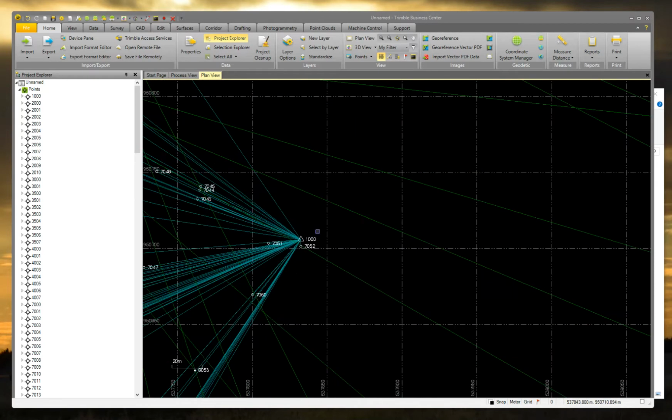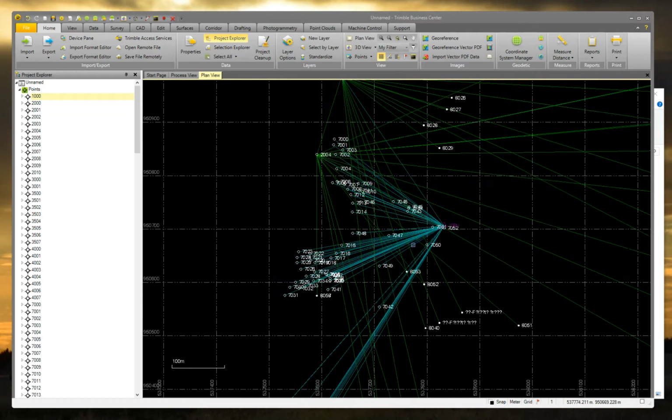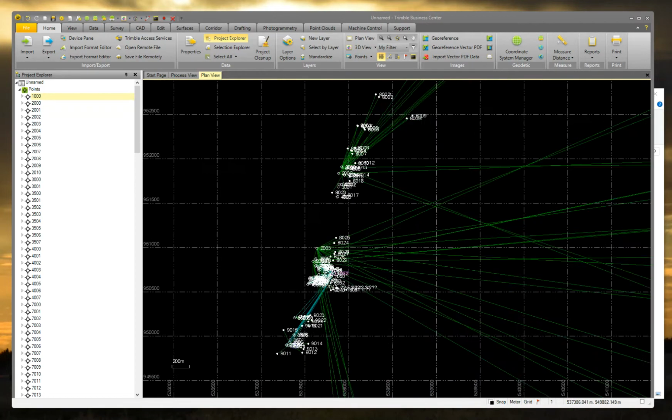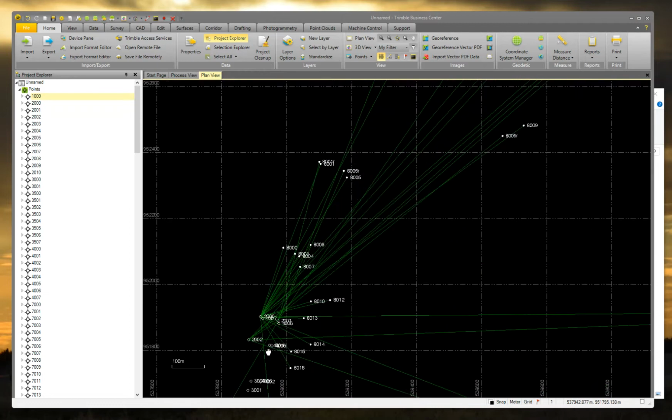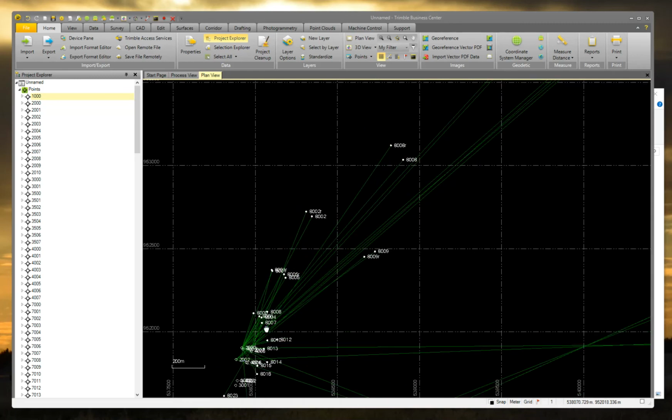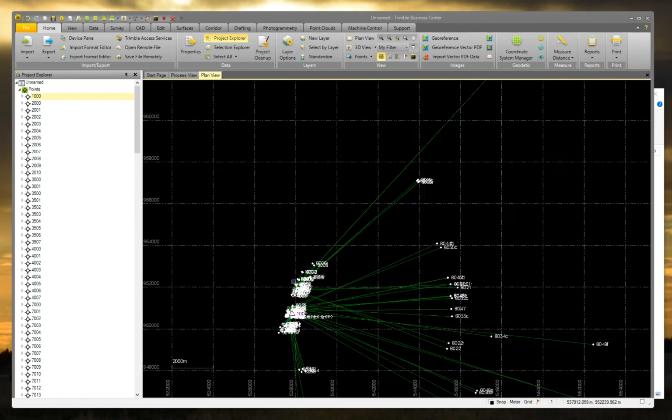You can see that your GPS base station 1000 was running. You've got a lot of unprocessed vectors here at various points. And up here, again, you set total station. I'm not sure why, but there aren't GPS files into this. So you should see these unprocessed vectors to 2000 and 2001. So that looks like a problem.